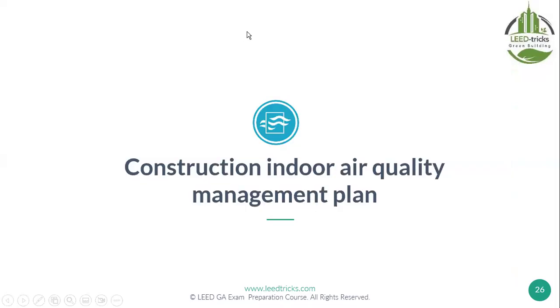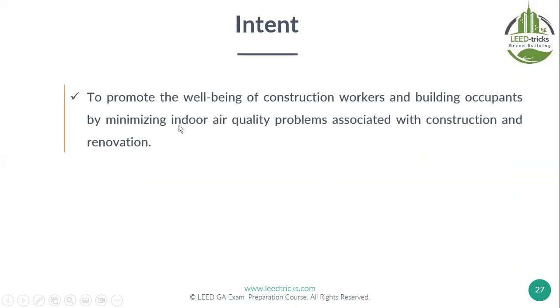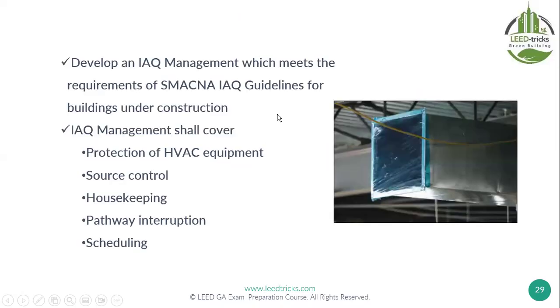This is the pollution within indoor, but what about air pollution during construction that can impact the operation later? The same intent here. As I told you, the intent is fixed: to achieve well-being and promote health for occupants. During construction, even though you install duct, maybe the dust comes inside the duct, remains there, and after that, when you operate the building, it will impact the air quality inside. So develop an IAQ Management Plan. What is IAQ? Indoor Air Quality Management Plan. How to manage the air quality during construction. This is one of the documents required from the contractor.